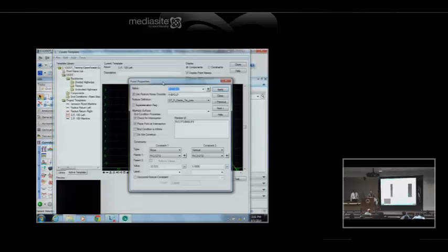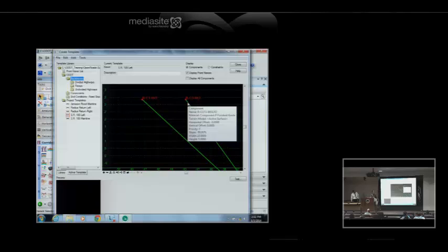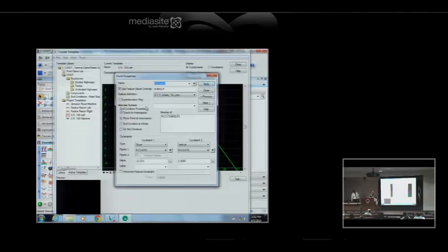So having these things connect, and in SS3 with OpenRoads with the template, having a feature definition that's assigned to them. I don't think that was there in Roadway Designer, a feature definition on a point. So I've gone back through this, and I still need to go through it again because it's so easy to miss one. And I've tried to unify the point names from template to template so they're the same, and the feature that's assigned to each point, I've tried to make sure that's consistent.